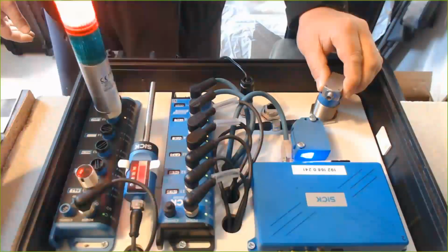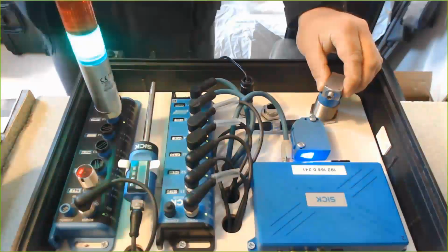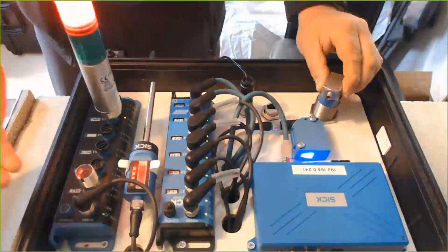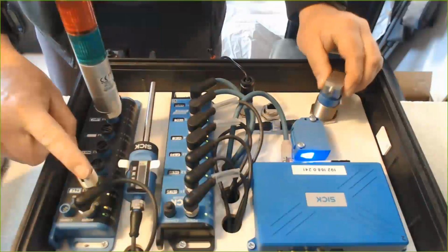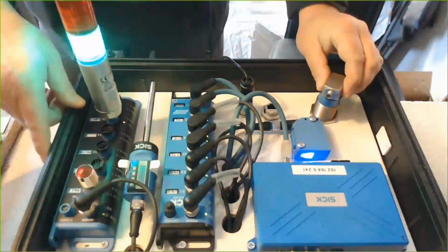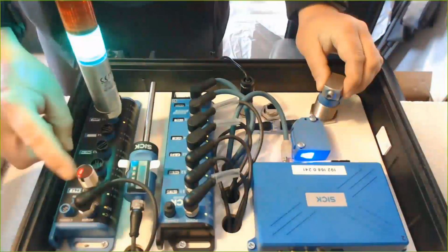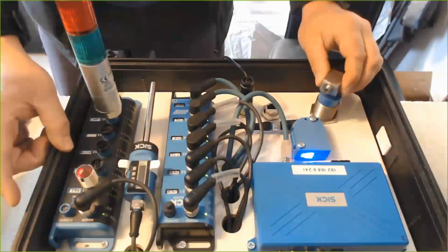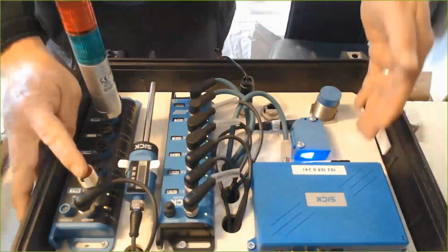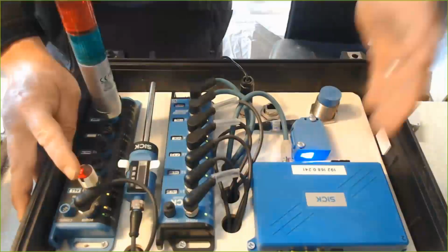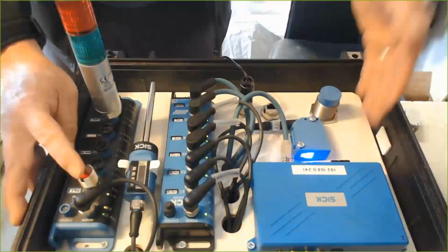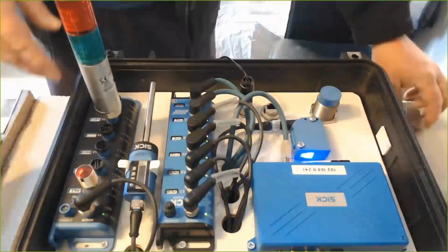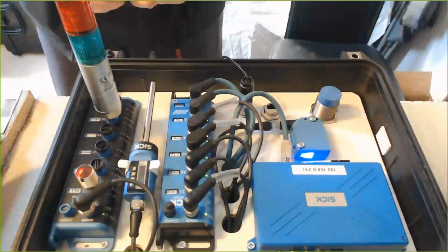Now, we're using a lamp to show this. Those digital outputs could quite easily go to any system you like. And we're just varying that around, and you can see we're getting useful information. But then if I cover the optical sensor, the inhibit sensor, it doesn't matter what I do with the metal target, it's being inhibited, as you can see there. So we've got an input being used via the SIG100 that's going through to the SIG200 via the logic and creating a useful system. I'm now triggering the optical sensor, and the way we're demonstrating that that's being triggered rather than the inductive is both lamps come on simultaneously.